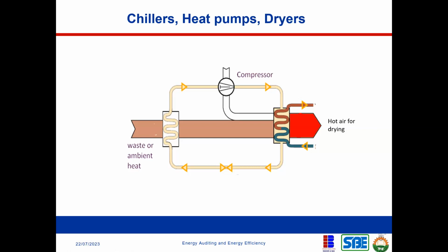And we know that a compressor produces coldness. I mean, sorry, your air conditioning system or a cooling system produces cold air, meaning that they extract heat, they remove heat to produce cold air. So at this point, this is your evaporator, you're removing heat. And at this point, instead of dumping that heat into the environment, you recover the heat and use it for your industrial process. That's what a heat pump helps us to achieve.